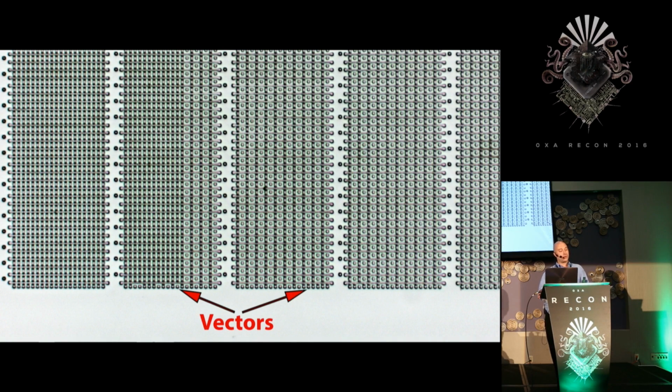This image shows the end of the ROM area, and we have a really large pattern visible here. This is because there's filler bytes that occupy the unused space at the end of the ROM. Then at the very end of ROM, this pattern is interrupted. This is because this is where the vectors table exists at the top end of memory. This is where they have the reset address and the addresses of the interrupt handlers and this kind of thing. So the ROM has empty space, all of these filler bytes, at the end, and then the vector table lives at addresses FFF6 through FFFF, right at the very end.